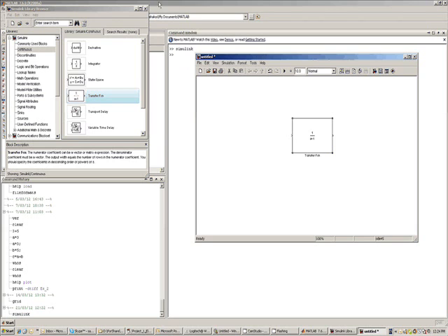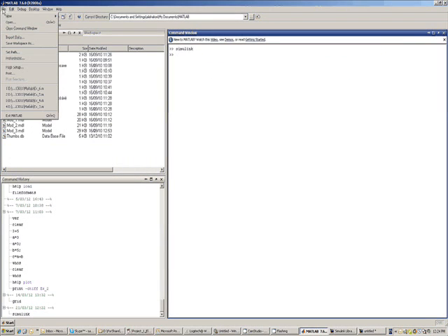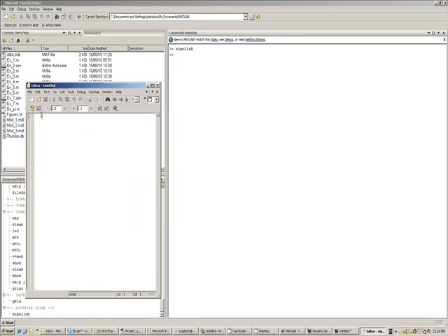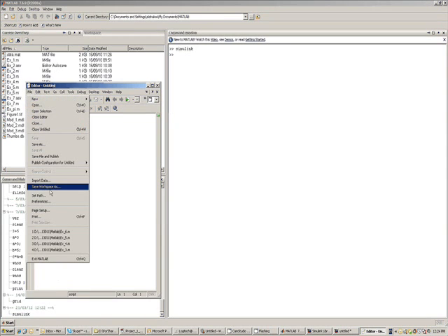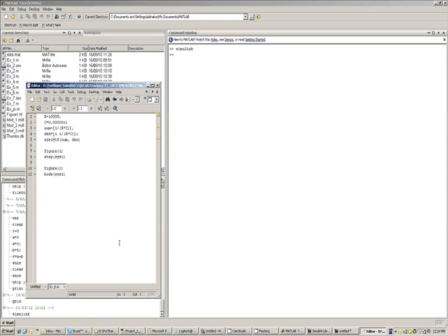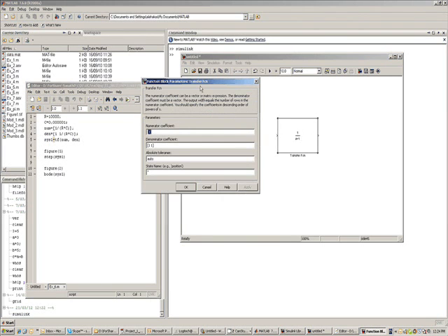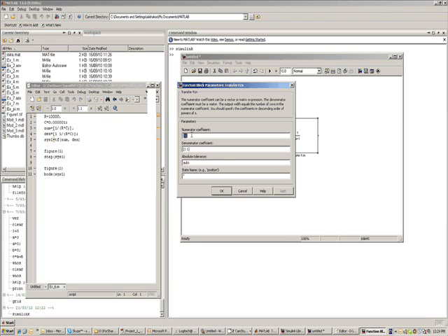Now what I'm going to do is, let me first open the M file that we have been dealing with last time, which is this one, I think. Yeah. And then let me find my Simulink block diagram. In this case, my numerator is 1 upon R into C. If I double click, you have separate places to define your numerator and the denominator.